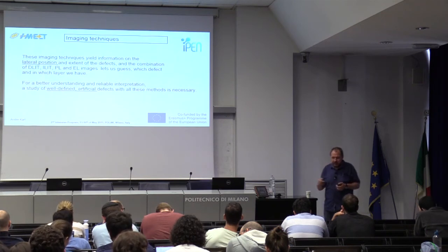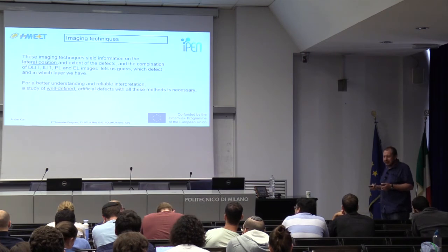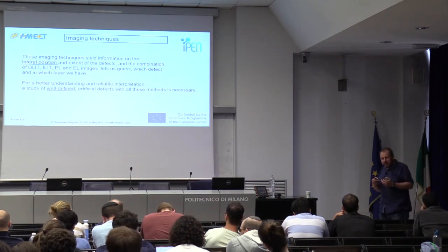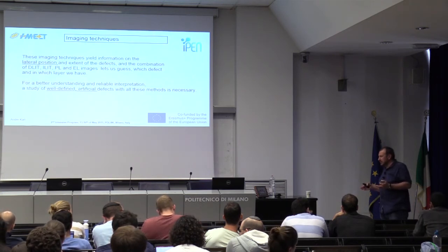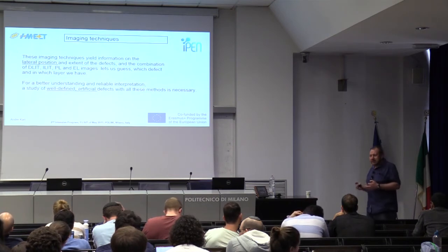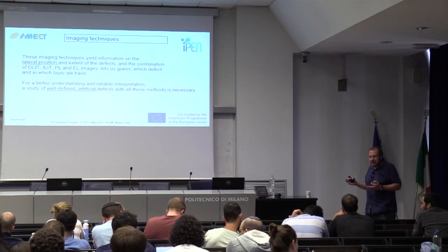You know whether they are left or right, up, down, but you don't know in which layer they are. You have a clue. If you think about what is going on, for instance, for photoluminescence, you don't need any contacts. So if something happened with photoluminescence, you know you have damaged the active material. If the active material is okay, but there is no electroluminescence, then you see that the injection of charges